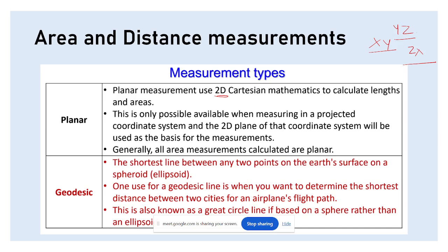So it involves doing the measurements in 2D. For example, if you have seen the survey topo sheets, especially from GSI, they give information about the kind of terrain, the contour, what kind of elevation is in that region, what kind of rocks and minerals are there.